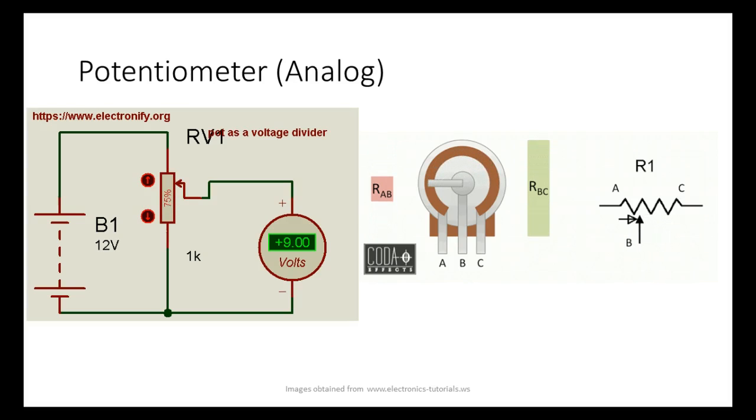So that means this potentiometer has got to give me an electrical signal. It cannot send resistance, can it? The sensors might vary a resistance, but then we're going to take that and convert it over to a voltage or a current. We don't like a lot of current in sensors because sensors create drops in wires, right? So the predominant method we use to send it is varying voltage. So that's what a potentiometer does.